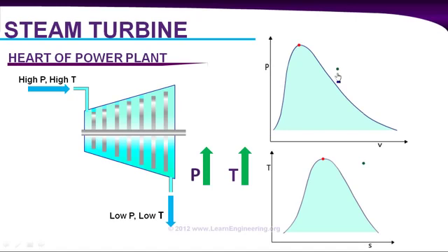And this is our starting point, a high pressure, high temperature steam. During this process, we know the pressure decreases. So in a pressure-volume graph, the pressure will come down. Since this is in a gaseous state, obviously the volume will increase with the decrease of pressure. So this will be the curve. It's an adiabatic process. And in the temperature-entropy graph, you know the temperature is coming down during this process, and there is no heat addition or heat absorption to the fluid. So this is a constant entropy process, and you can draw it like this: temperature is coming down and entropy is constant.